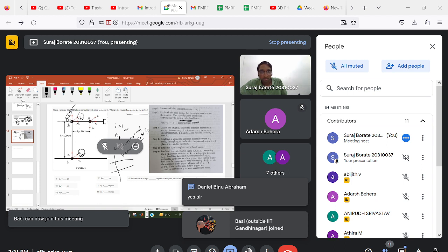Now let's move on to i equal to 2. What will happen if i equals 2? Common normal between z2 and z1. Z2 we already had. How did we get z2? We just put z's along the joints. You don't think, you see if it's a prismatic or a revolute joint, just put it along the joint. Along the joint you can put it inside or outside. Someone would put it like this, no problem.